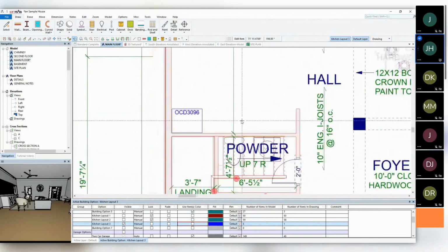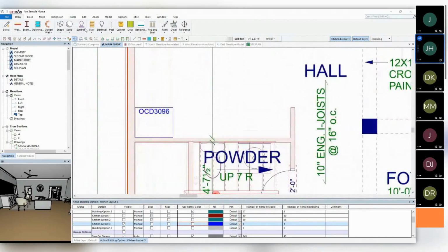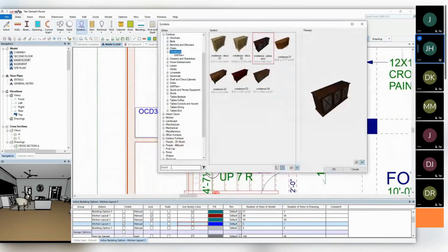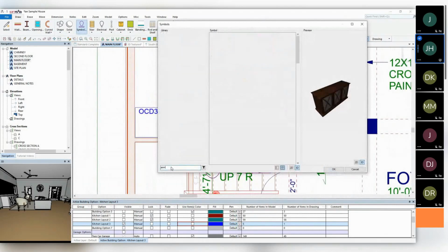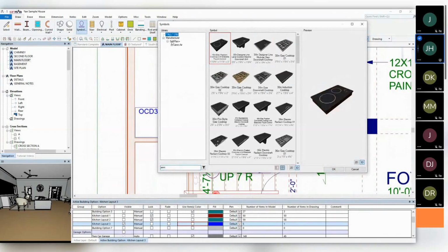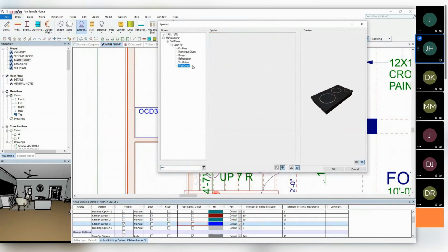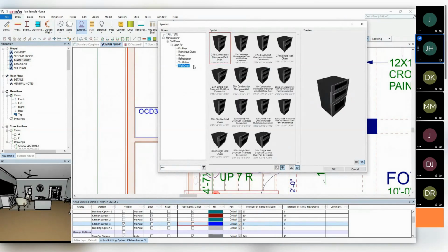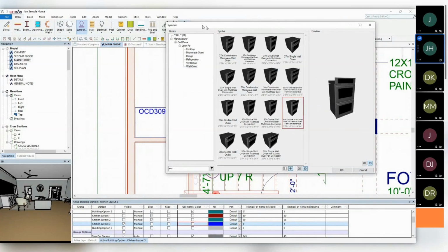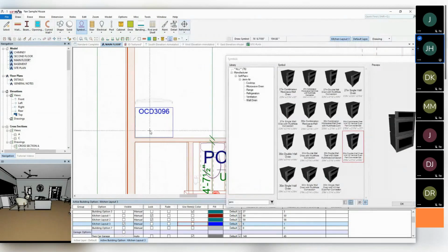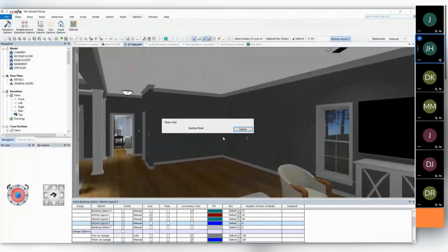Okay, so as I continue with this, I'm going to come in through draw and symbol, and I'm just going to do a search for, let's say, Gen Air, as being my manufacturer that I'll use today. As I come into this listing of manufacturers, we've got our different ovens that are here, and so I can select a wall oven, and of course I'm looking for something that's 30 inches in width. This is a double oven, and once again I'm drawing it inside kitchen number 3 as far as the layer is concerned. I can click to add that in, and as I look at this inside 3D, it's going to begin to build that model for me.